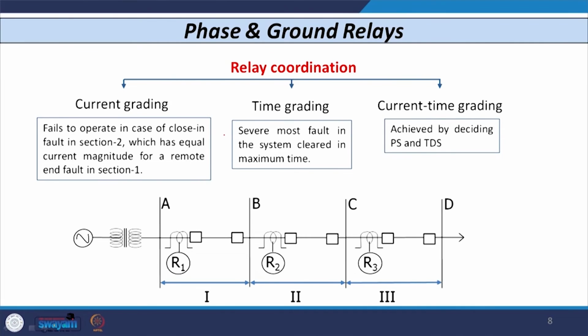That procedure is known as coordination of relay. When we carry out coordination of relay, we have to follow some procedure, and we always start the setting of those relays which are located near the load end. This is also known as the downstream end of the network, and as we move further towards the source end, also known as the upstream end of the network, we have to progressively decide the setting of other relays. So, let us see how the coordination of relays is carried out.